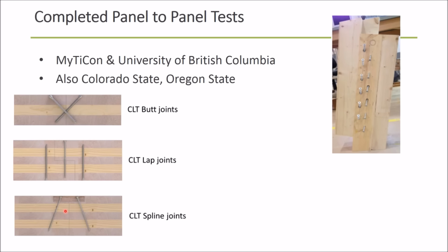That's very much different if you took those same two screws and skewed them, if you will, in and out of the screen. So when that shear plane starts to move and those panels try to shear against each other in and out of the plane of the screen, those screws are in tension and compression, not just pure shear dowel bearing. Those are very different behaviors, and those same two screws respond very differently depending upon those.